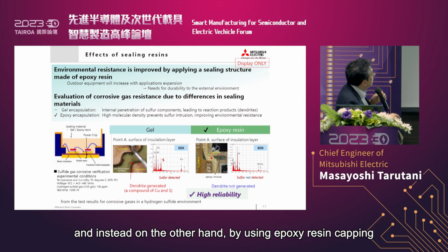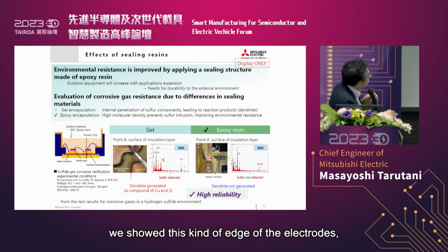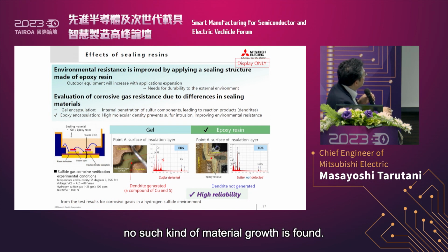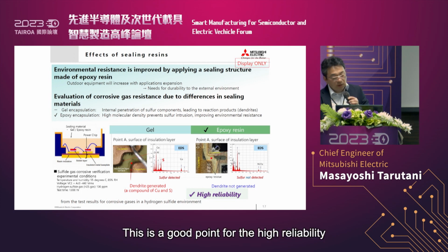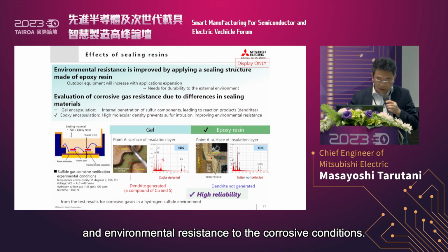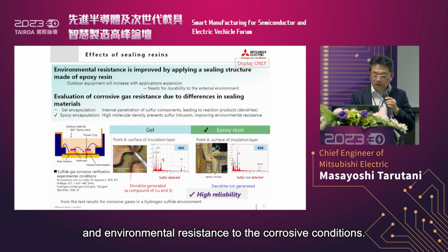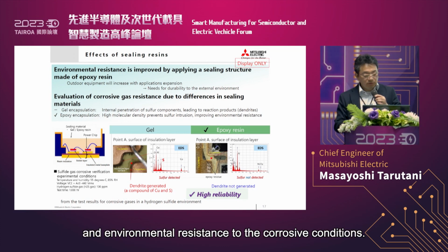On the other hand, by using epoxy resin capping, I'm pretty sure that at the edge of the electrodes, no such material growth is found. So this is a good point for high reliability and environmental resistance to corrosive conditions.